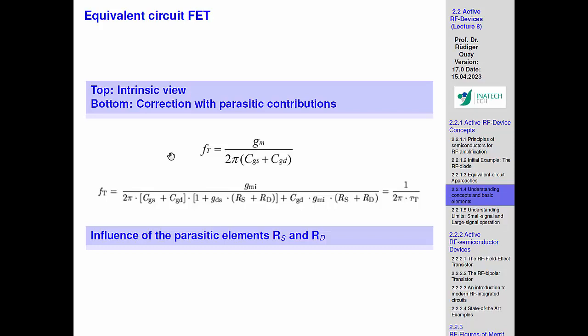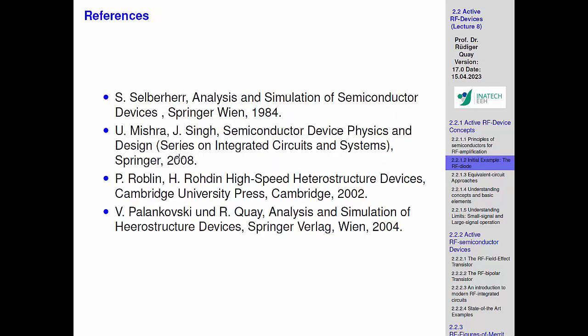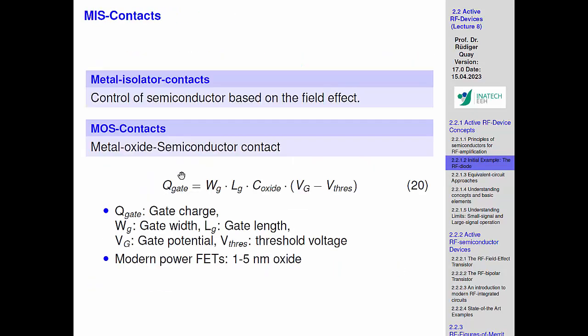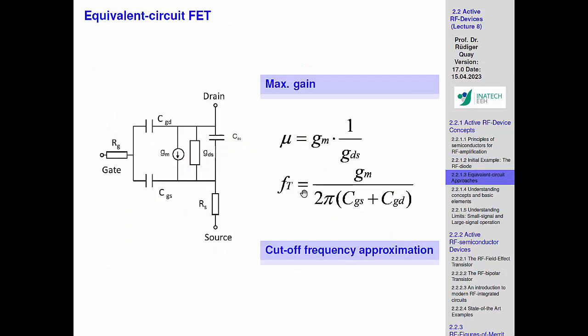And then I have two capacitances, and the CGS. This is the gate source capacitance, essentially this capacitance. Yeah? There's also a second component because we are directly including that. So in first order, you could even cut that feedback capacitance out. But typically we include that because it's always a 10% effect in the whole story. So it's always wise to include it. Yeah? So it's also charged and discharged. So that's why it's directly in.